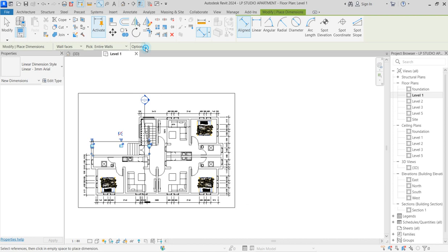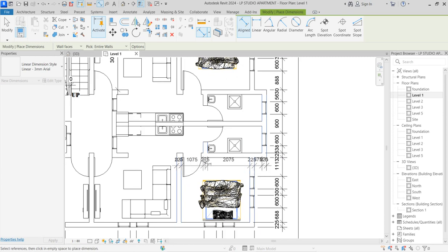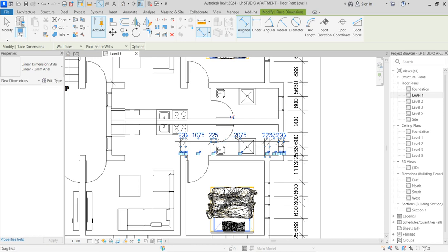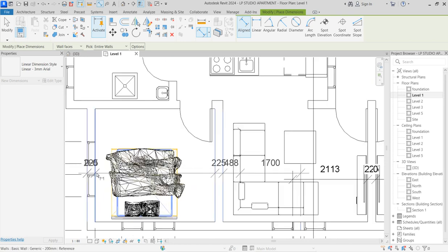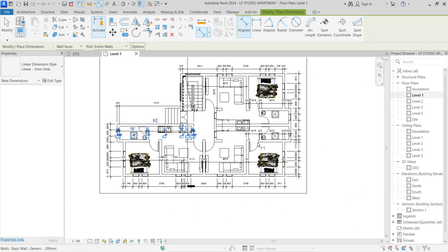Now, as you have done with that, you can decide to change again. What are you doing? Wall intersection. So click like that, so you don't want opening. Can you see? It's going to give you the wall, the width, and the intersection part of it. You can just imagine if you add the dimension to it. This will help you to get your details right. So that's how it works, and it gives places for the eyes to see. So that's a quick method of doing dimension in Revit and things like that.